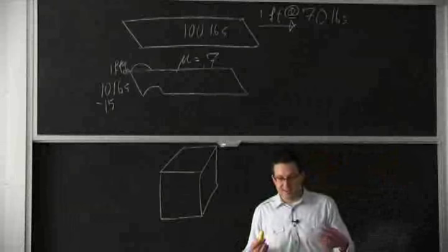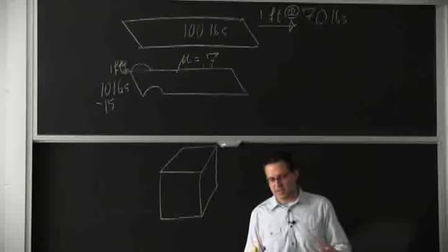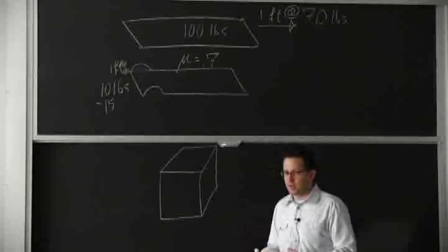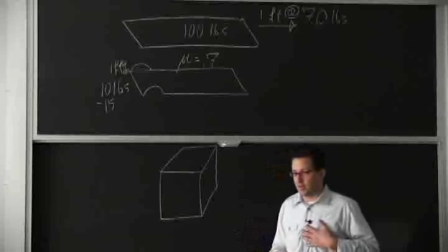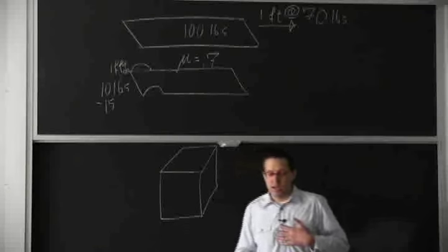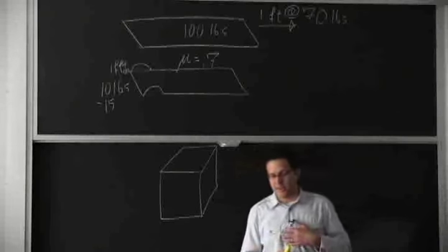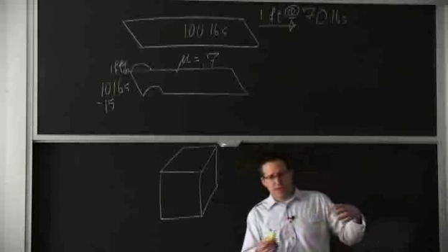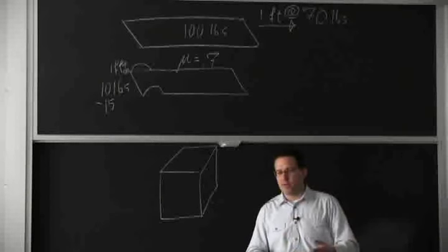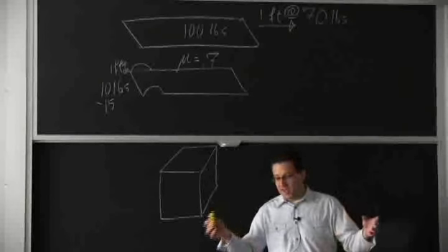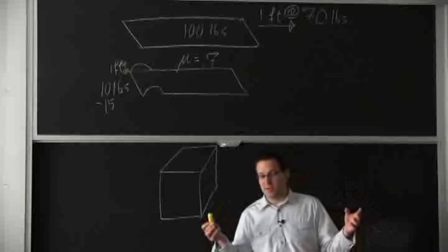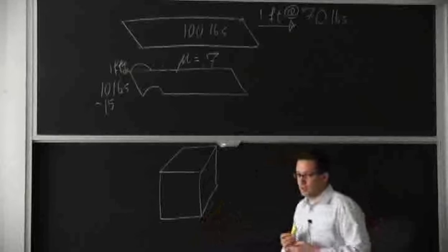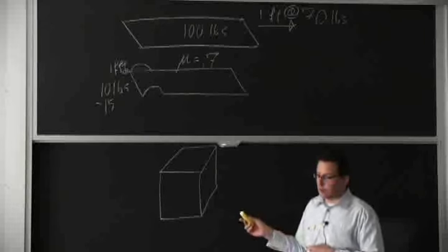And the state, the condition of the stress shouldn't depend on how I draw the box. So that's just my way of looking at it. It's the same way if you do a free body diagram in a static problem. It doesn't matter if you cut the problem in three and bring it back together, if you have enough pins that your system only has one solution, you can do it the way you want. And it's the same thing here with that cube.